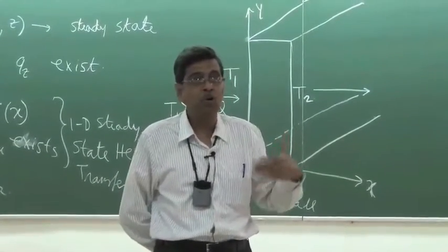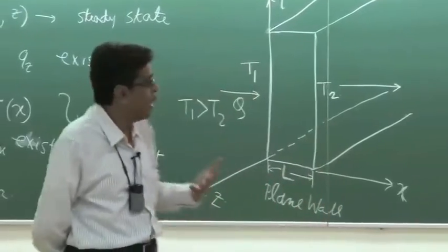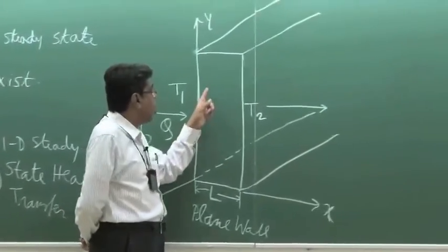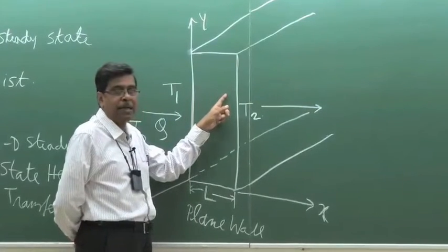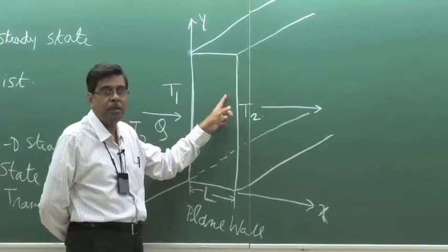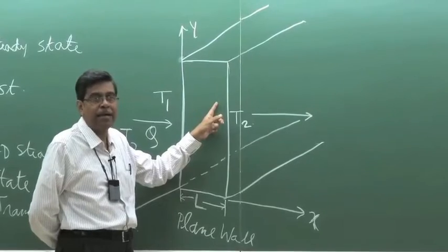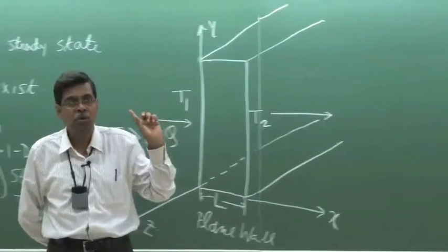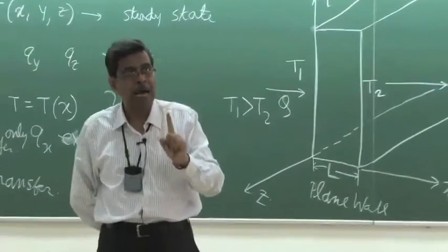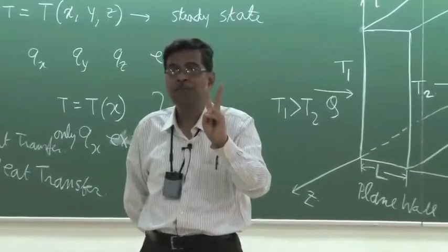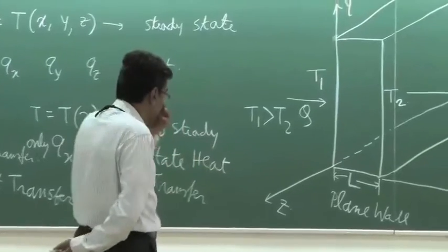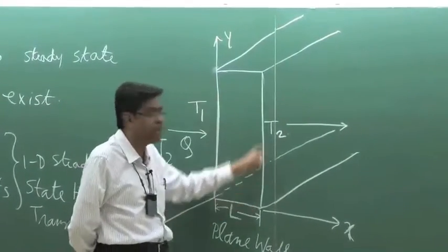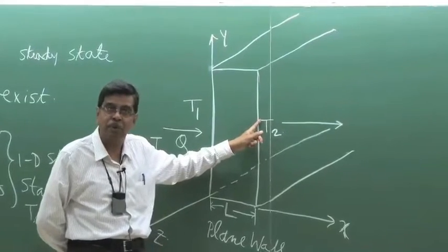Now, how to conceive of a steady state? By basic understanding of the steady state, at all points the temperature has to be invariant with time. There may be a distribution, but invariant with time. So to meet that, we have to have two physical requirements. One is that definitely the boundary temperatures have to be invariant with time, which I have prescribed for this problem.